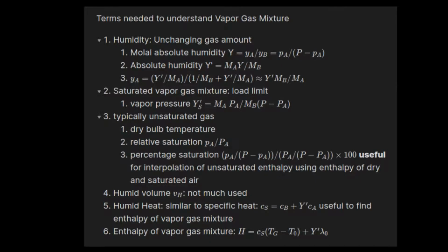Let us now increase the complexity by adding air also. For this binary mixture, how can we define its properties based on the pure properties which we studied now? So for this, let us study some essential vapor-gas mixture characteristics. The essential characteristics that are required to understand humidification are humidity, which is the amount of water vapor present in the air. So for composition, we typically use mole fraction, but here the amount of gas, that is air, does